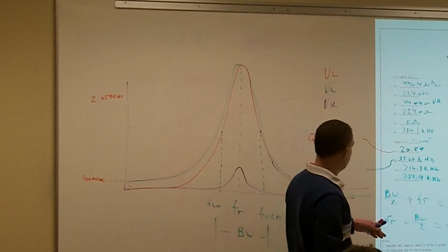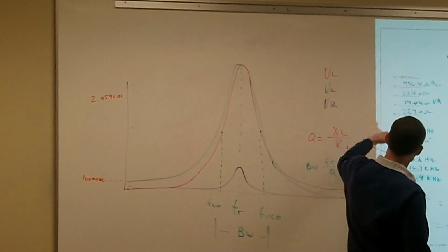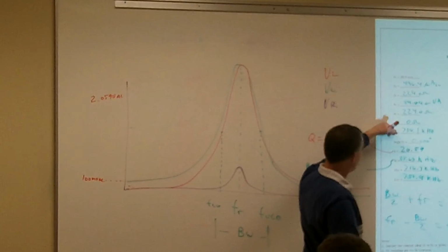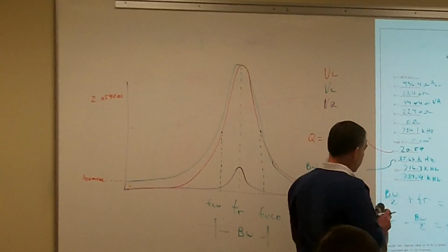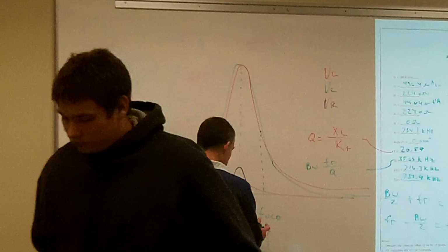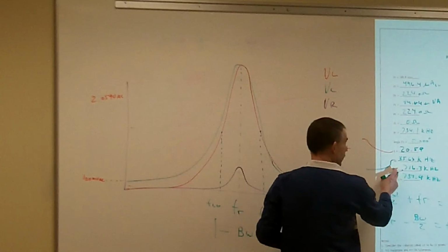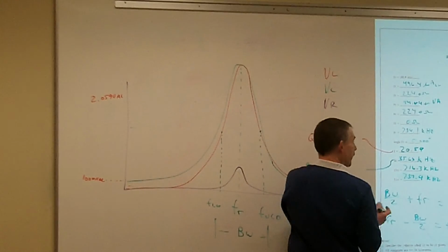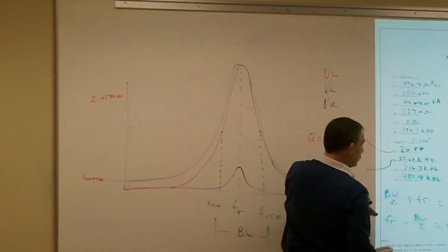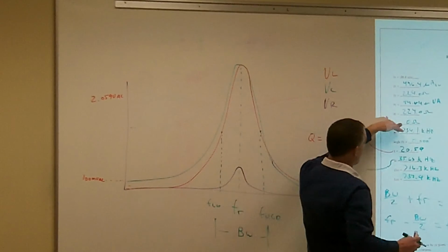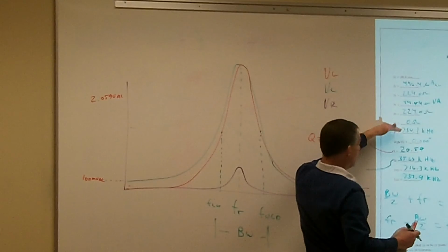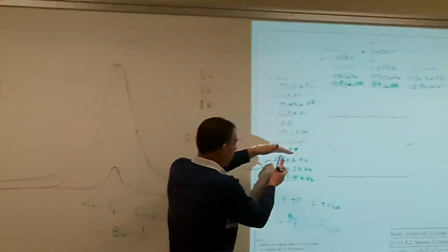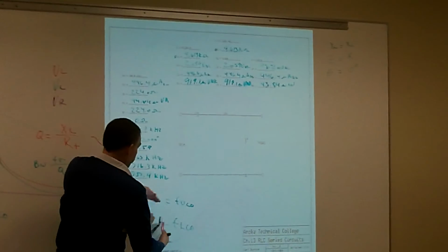So if I had a radio station that I'm going to listen to, the resonating frequency I'd be tuning into would be approximately, let's just say, 734.1 kilohertz. But my radio would actually tune into anything between 716.3 kilohertz and 751.9 kilohertz. We have to have some kind of bandwidth in there so that I don't have to tune my radio exactly to that precise frequency. Otherwise, it is going to drift all the time and you would never be able to maintain your radio station. We have to have allowable bandwidth.